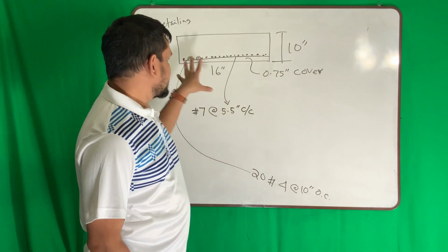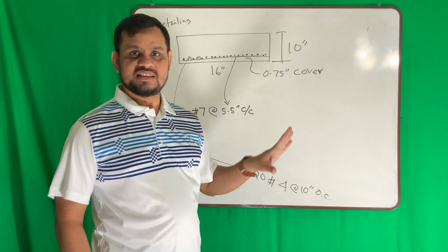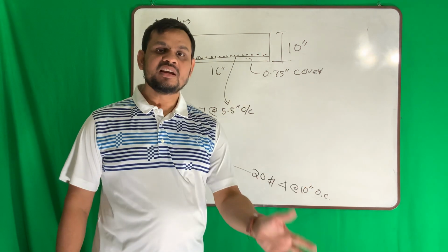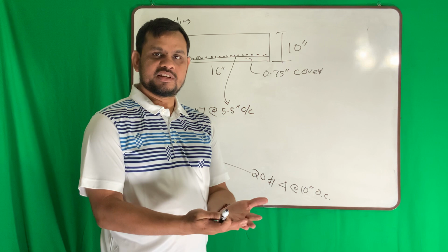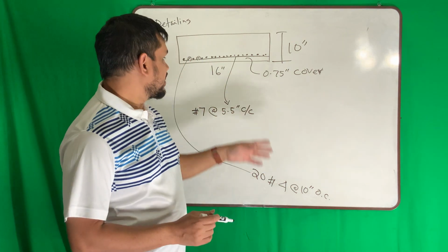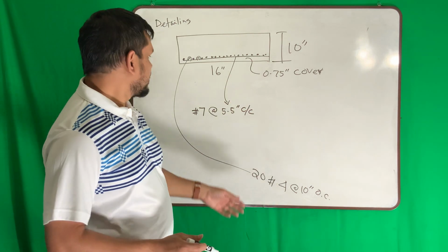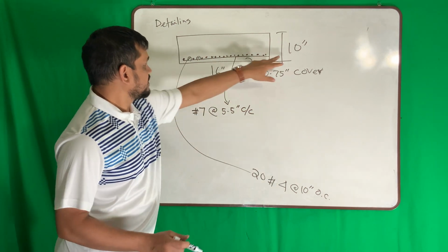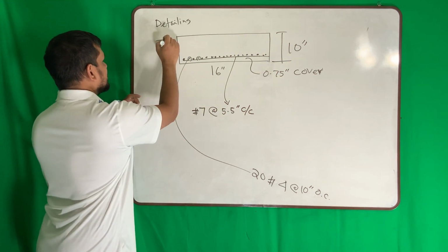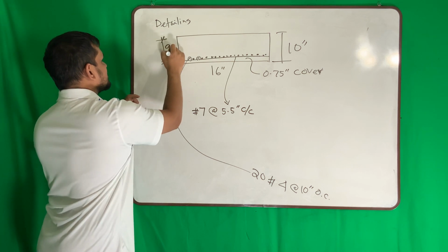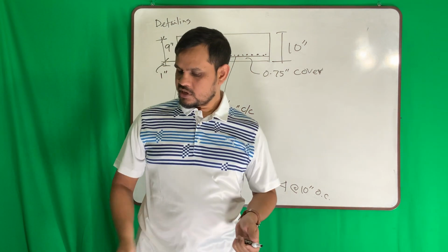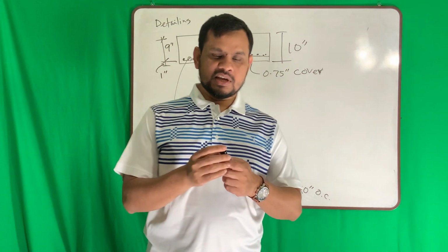But do not forget to present your answer in a very neat sketch. Very neat sketch. Who will use this? Your field labor. Your field labor will see this sketch. So make sure it is very clear, clean, and maybe you can duplicate your information. So somewhere you wrote this 10 feet. A different way you can, even this side here to here, say it is 9 inch. Here to here 1 inch. So present your information in different ways so that the laborers can follow.